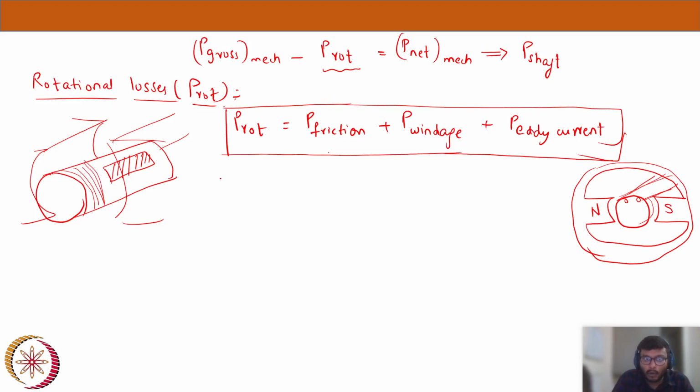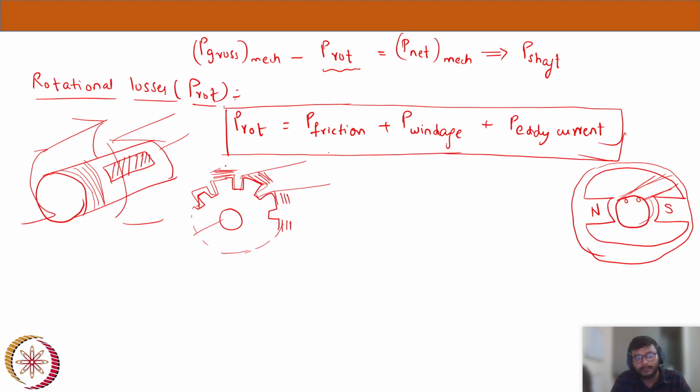Let's say our rotor structure is like this. The rotor will have its slots and teeth like this, and the shaft will go here. They make this structure as a single sheet, then make another sheet and place it behind this lamination. Like this, they make a number of sheets and place one behind another, and that's how they make the entire structure of a machine.